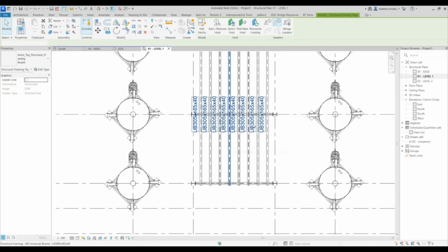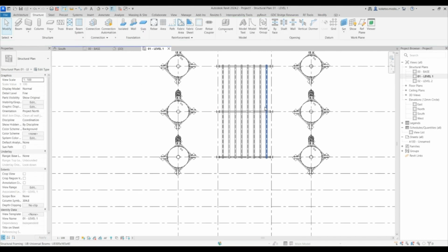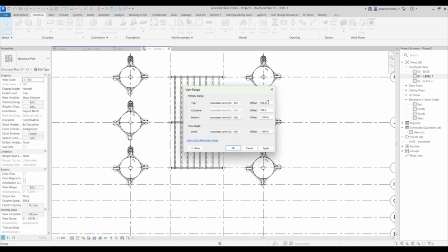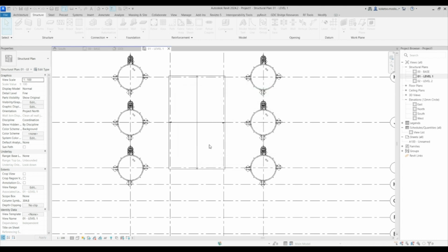I think they're making things, yeah. So you can just remove those annotations. And after this, you can just set your VR to 4,000 millimeters and your cut length to 4,000, say apply and then okay. So perfect.